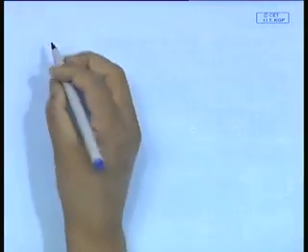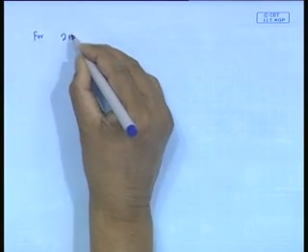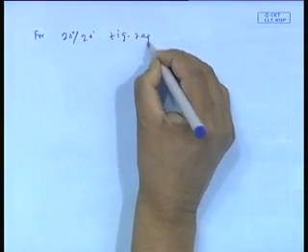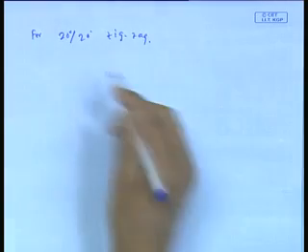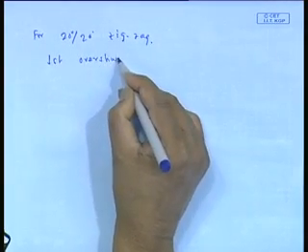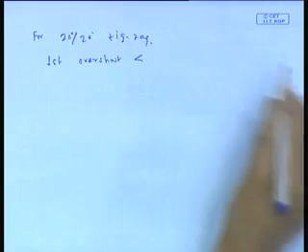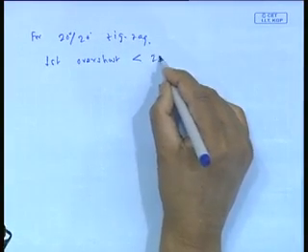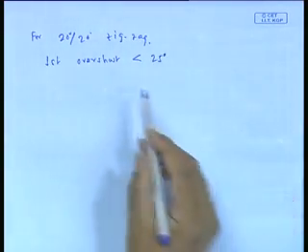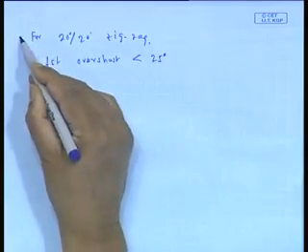Exactly the same stipulation, I will just have to write very quickly, for the 20-20 maneuver, because we are doing a 20-degree zigzag. It says the first overshoot should be less than 25 degrees. It says that in the 20-20 maneuver, the first overshoot will be less than 25 degrees. That is the other criteria.